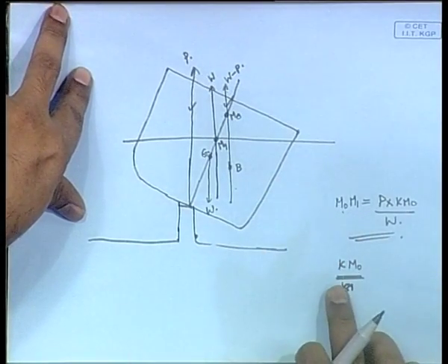Of course you need that to do this problem, but once you design a ship, you design all that, so the initial design comes with you, this is known as the hydrostatic curves, the whole thing comes with you. So you look at that, you find the displacement at each draft, so you find the change in displacement. The change in draft you can always read, in any dry dock you can easily see it. Read the change in draft, read from the hydrostatic curve, find the change in displacement, find the change in weight, that is P. That will be borne, when the ship touches the ground, by the weight of the keel block, that will take the weight. So this is the first way of doing it.